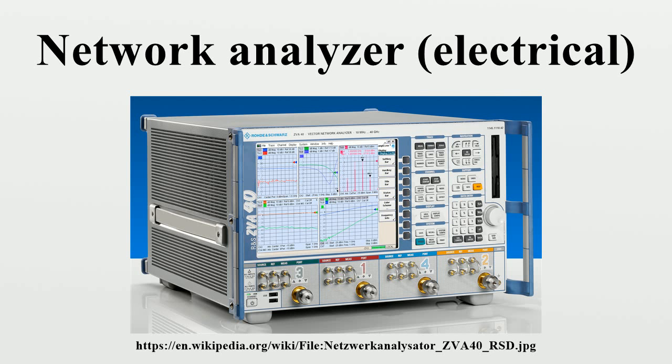In a typical one-port reflection calibration, the user measures three known standards, usually an open, a short and a known load. From these three measurements, the network analyzer can account for the three errors above. A more complex calibration is a full two-port reflectivity and transmission calibration. For two ports, there are 12 possible systematic errors analogous to the three above. The most common method for correcting for these involves measuring a short, load and open standard on each of the two ports, as well as transmission between the two ports.